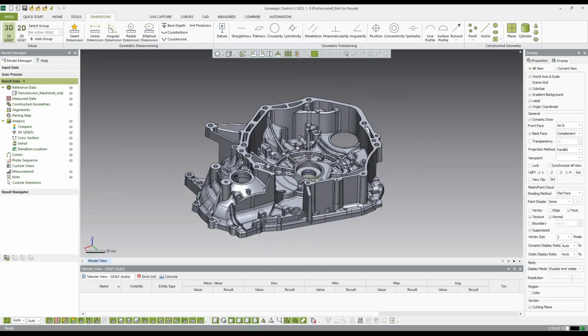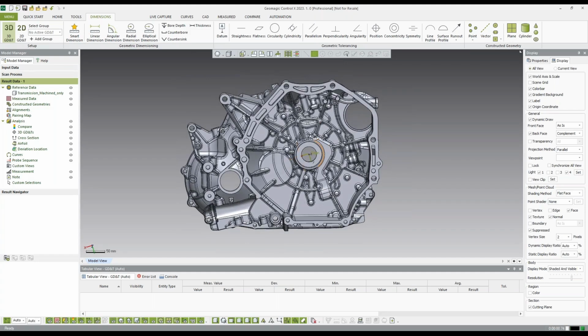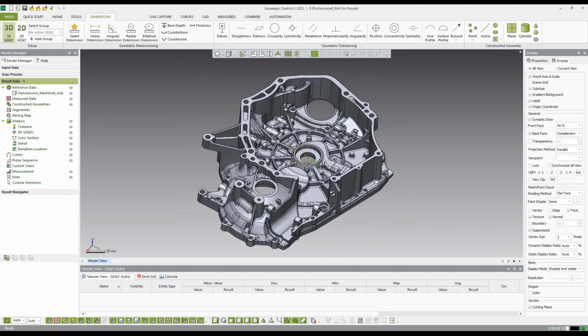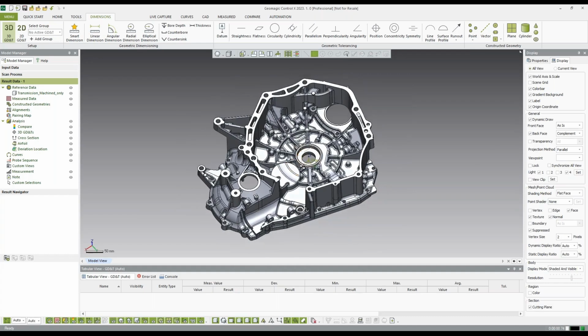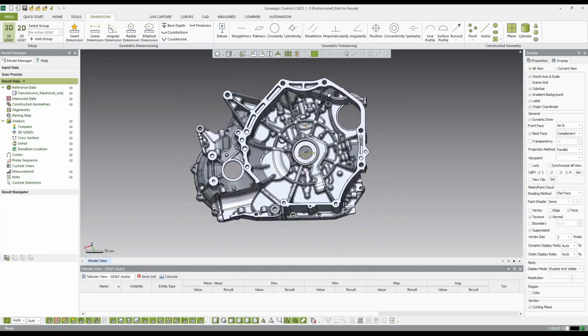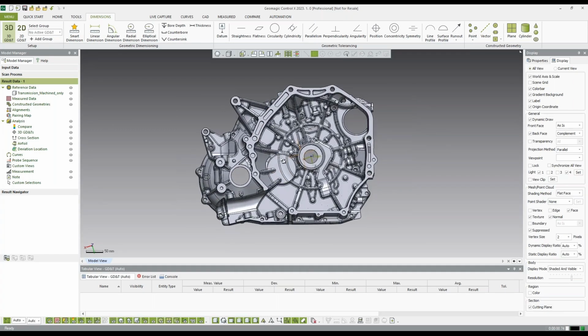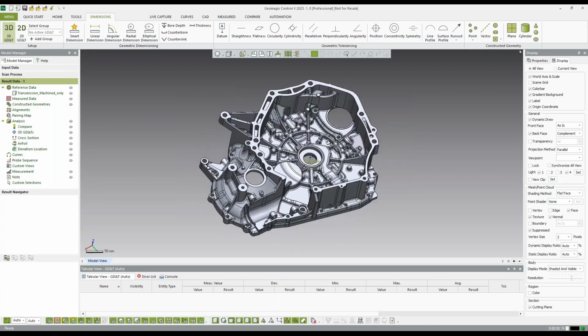So what I usually do when I set up is think about what is my first thing on the print? What's my first big section that I want to do? Is it something top down, or is it from a cross section that's the most interesting, as far as what the main aspects of the drawing are? For something like this, we'd probably start on the top face, just because there's a bunch of holes to call out and positions and stuff like that, or we want to set up some datums here.